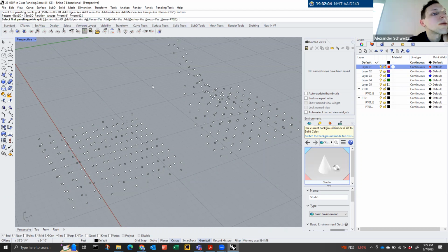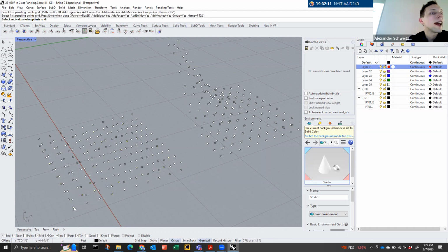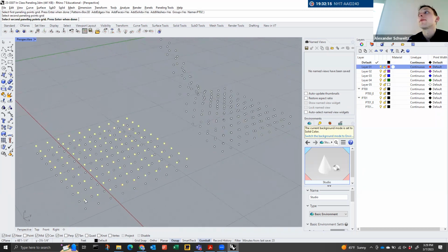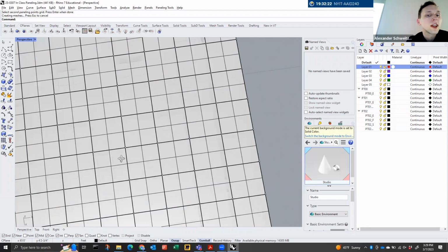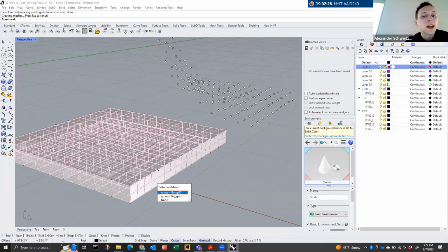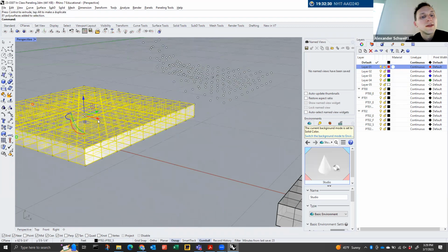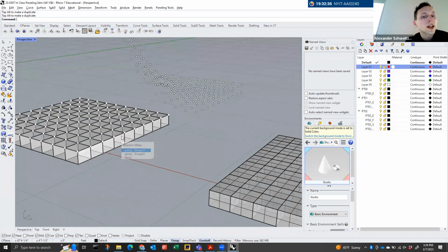Add faces, name. All right, select first paneling points grid. That's the bottom. Add second paneling points grid. That's the top. Enter. It now created my 3-dimensional box using boxes. And I also turned the meshes on, so it gave me a group output like so. See all this junk that it made?